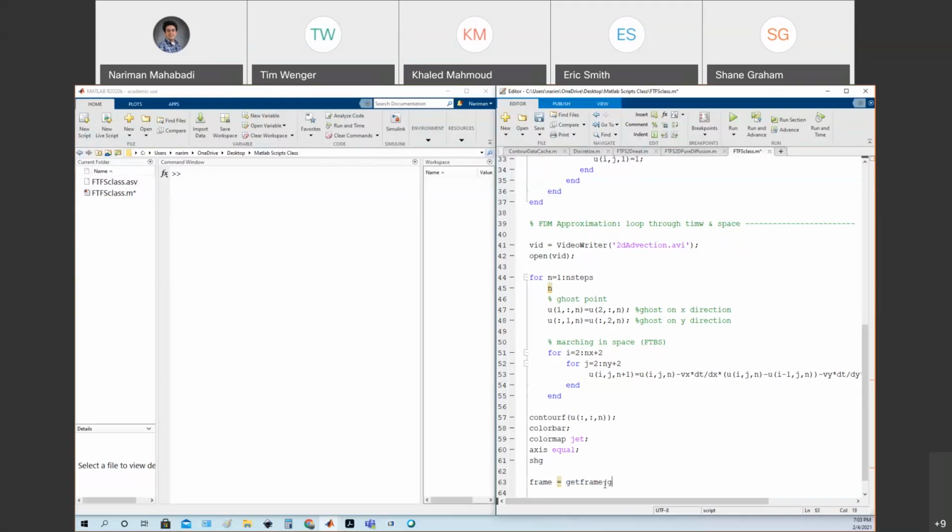You need to write gcf. If you don't know anything about any of these functions or variables, go to the help of MATLAB and you're going to see a lot of information. But anyway, gcf means the current figure, the current graphics frame. So it gets the current frame and puts it in this variable. I call this frame. You can type FR or anything, it doesn't matter. But these two should be exactly getframe and gcf. And what next?